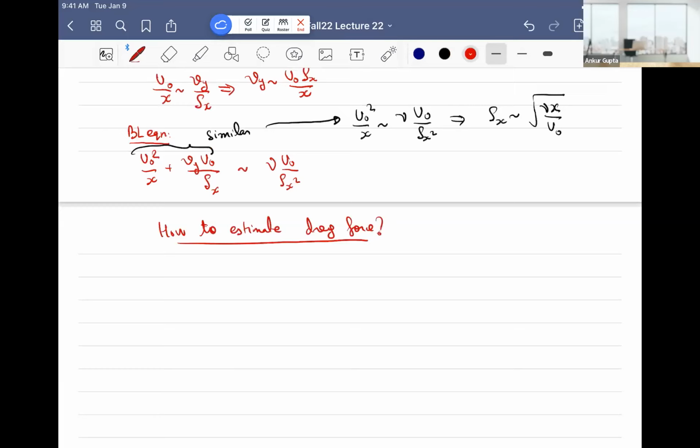Great. Does everybody see why? So what Tim is saying is, first, I hope all of you can see this, that because of the geometry, let me just sketch this plate like this. We're flowing something on the plate, right? I am not talking about the perpendicular force when I talk about the drag force. There are two parts, pressure and shear stress. Then you can calculate a stress vector and calculate both the forces. But because the geometry is such, and you can do the full calculation, it's not required. It's obvious that if I'm sliding something on the surface, and I'm just shearing the surface, I'm not applying a normal force. That is not true for other geometries, and that's why we have moved away from the cylinder for now.